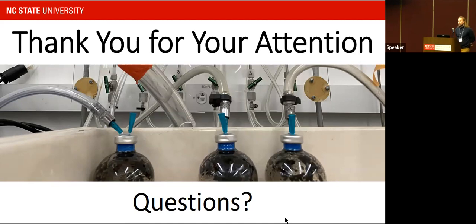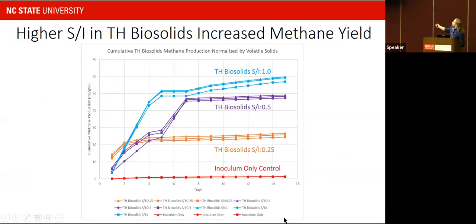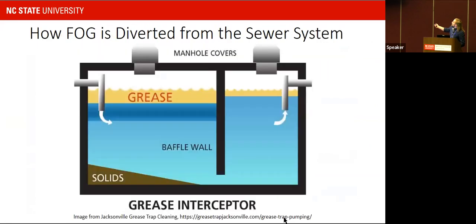Any grease that you put down the drain will combine with ions in the sewer and harden. This is to say that food services have grease interceptors that collect this. These grease interceptors are maybe 1,000 gallons or more, so there is a huge amount of grease in there. In fact, if you came off the highway to get here, all the fast foods you pass, there are several grease interceptors in the ground. They have to be, because we have to divert FOG.